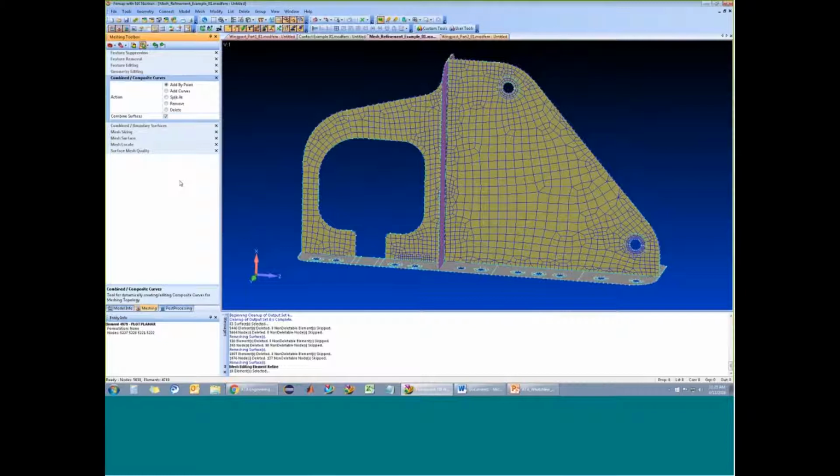But now we have options to actually edit the parasolid geometry within the toolbox. So this would be a permanent change that you can't easily clear or delete. You still have the old options if you want that ability to go back. But if you want to actually make changes to the geometry, then you can do that as well. So those options are under feature removal.